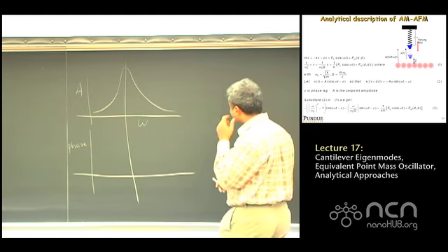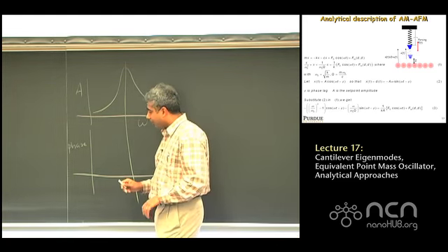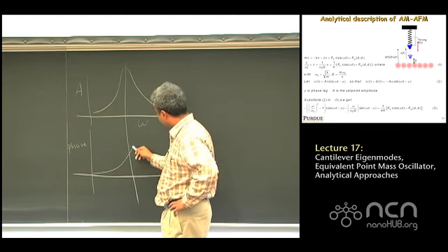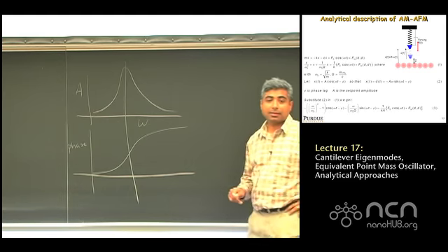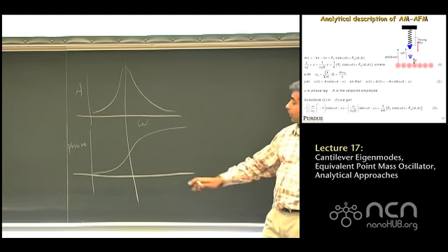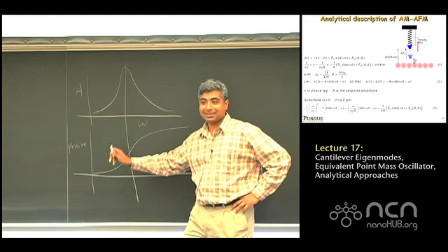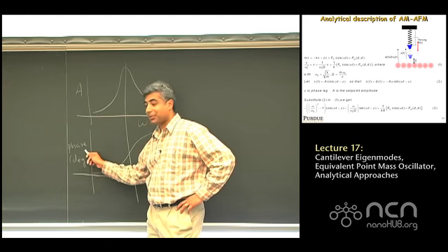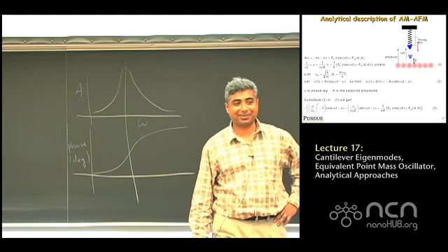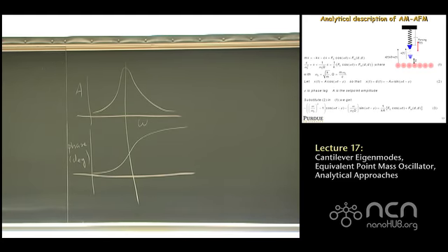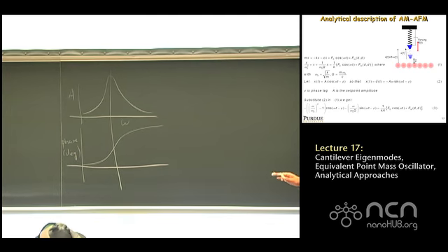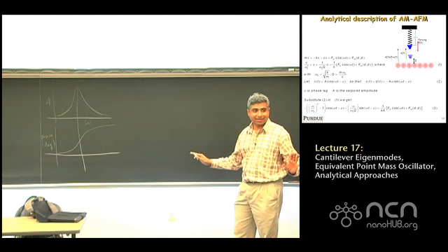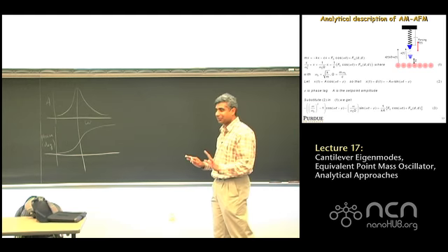You plot that. And if you find that it does this, right? That is, whatever number it's plotting, hopefully it's in degrees, okay? If it's in volts, again, I'm going to get very annoyed with you guys showing me these things in volts, okay? So degrees, make sure it's in degrees. Luckily, all new AFM systems automatically do it in degrees. In the older ones, even the phase would be in volts, so terrible. Trying to convert that into degrees would be terrible.